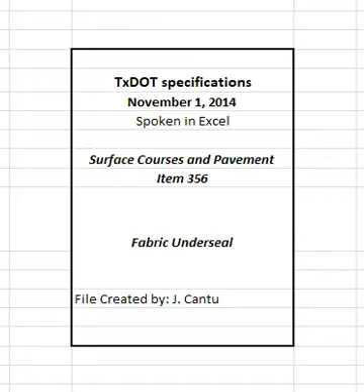4.1.3 Fabric placement. Align the fabric and broom or roll it in place immediately after asphalt binder application. Cut the fabric, overlap the cut fabric to create a transverse joint, and begin application again if skewed alignment occurs. Roll or broom fabric onto the asphalt binder in a manner that prevents air bubbles from forming under the fabric. Provide an alternate means of securing the edges to the pavement if wind prevents proper adherence of the fabric to the asphalt binder, especially at the edges. Cease underseal application if it is determined that wind conditions prevent proper placement.